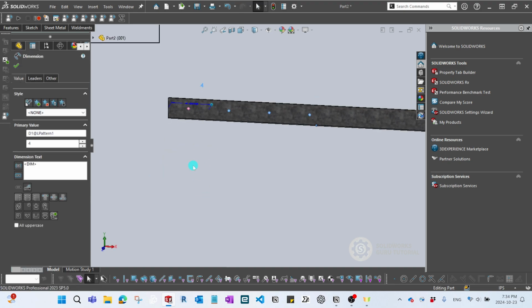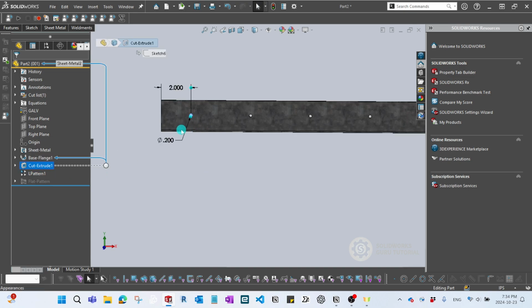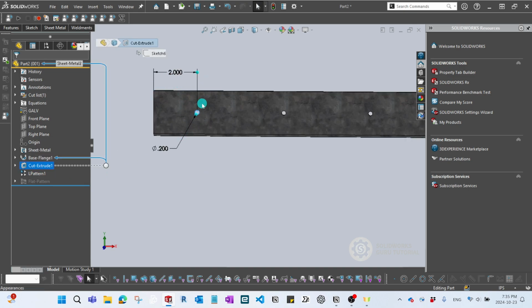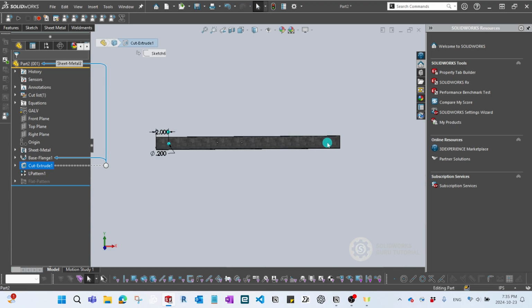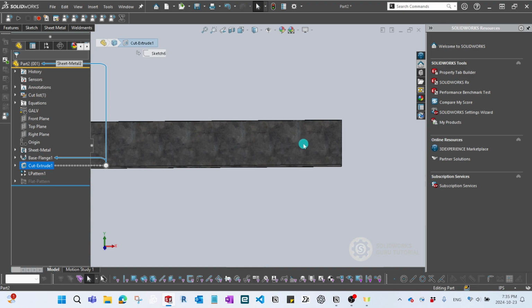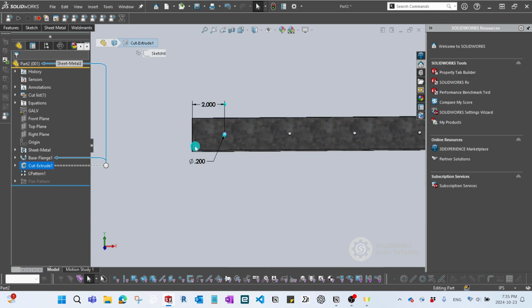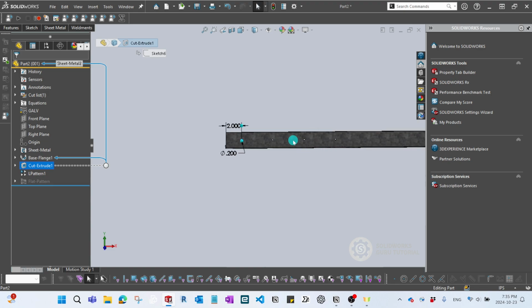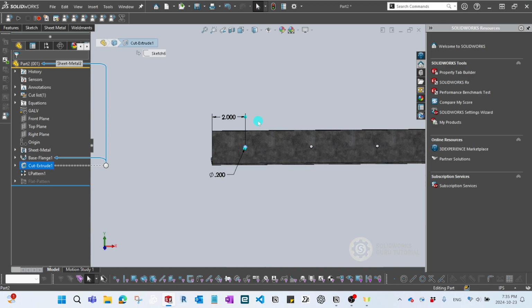So how are we going to do it? Let's think about it. If we have a look at the first sketch, we assigned 2 inches as a safety gap, because it doesn't really have to be in line. We can put enough gap to guarantee some space away from the edge. What that means is, on the other side there should also be 2 inches, so it should be symmetric. For design for manufacturing and assembly, DFMA, I think it's always best practice to make the part as symmetric as possible, so you don't get confused with a left-handed or right-handed version.